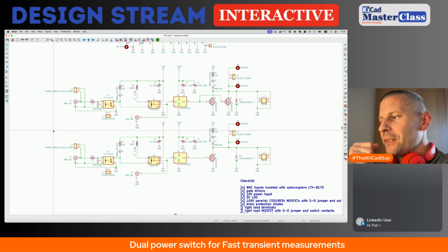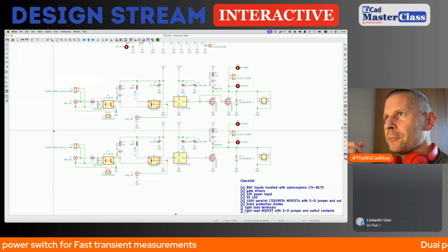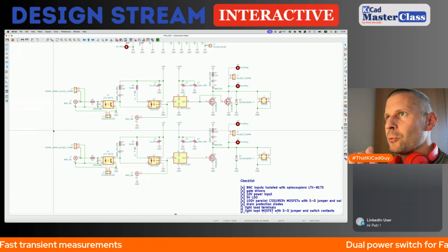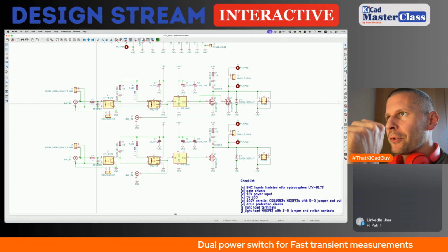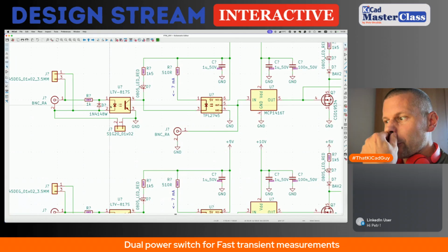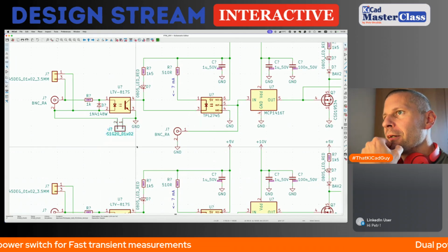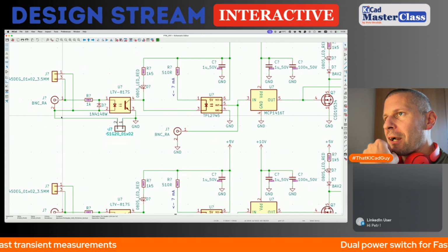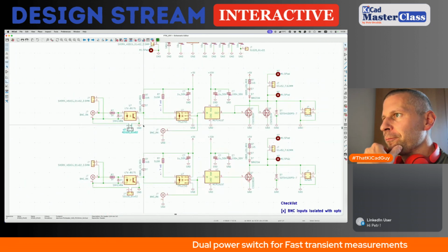We have the BNC at the input. We have the possibility to connect the signal on the two pin header. There is a protection diode for the optocoupler LED. There is possibility to connect the ground side of the BNC with the ground of the system.